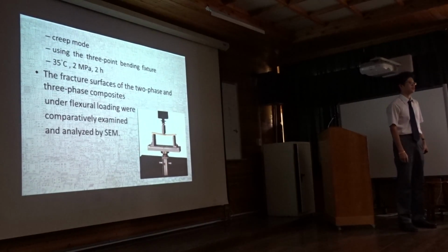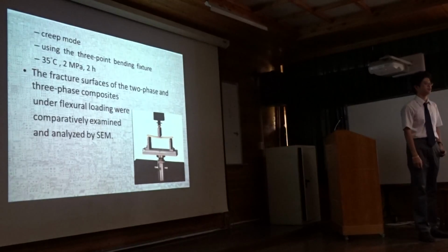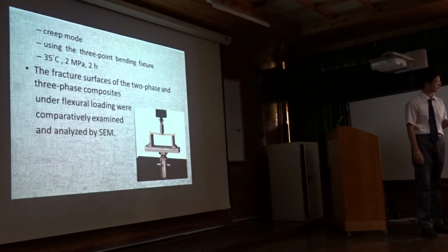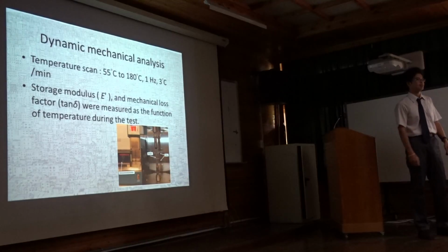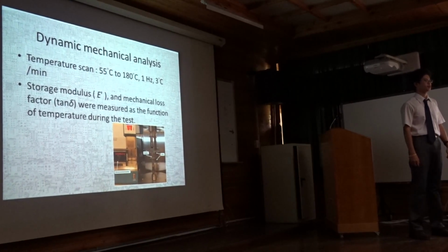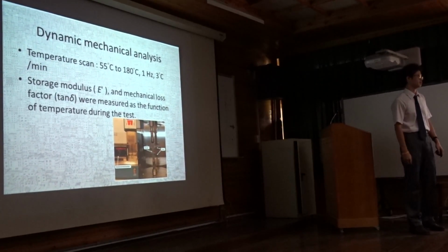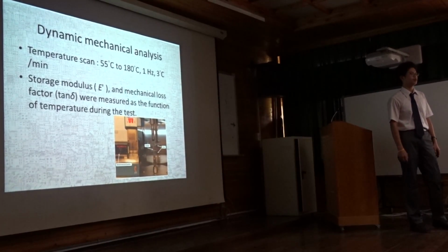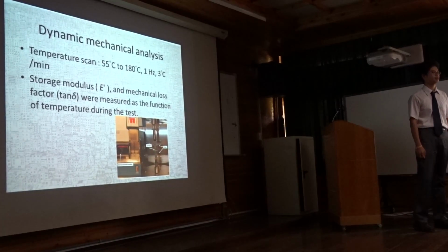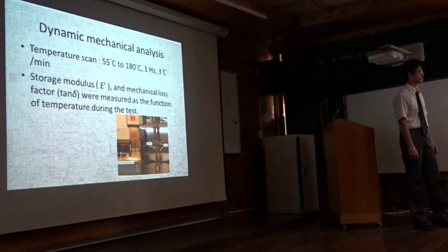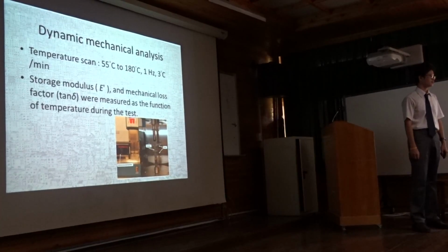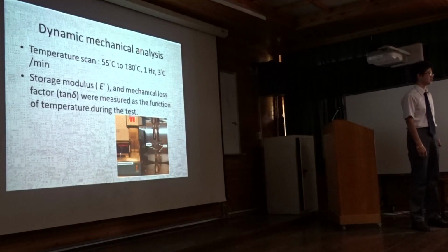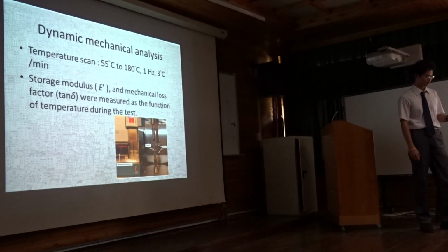The fracture surface of two-phase and three-phase composite under flexural loading were comparatively examined and analyzed by SEM. The same sample dimensions were also used in dynamic mechanical analysis. Temperature scan from 55 degrees to 180 degrees with a frequency of 1 Hz were performed. The heating rate was 3 degrees per minute. Storage modulus and mechanical loss factor were measured as the function of temperature during the test.